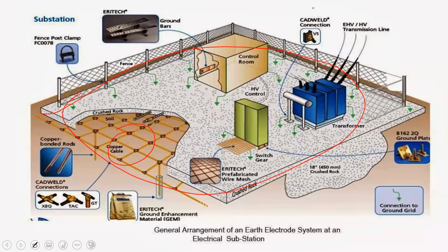So I want you to note that here we have the switchgear. That would be your breaker. Note you have a mat. When you're working on any piece of equipment within the substation, there will be a little metal mat that you need to stand on. And that's for your own protection, even though you have on safety boots, etc. And that is the switchgear. And you saw the little green thing there? That's showing you that it is connected to earth. Your transformer, connected to earth.